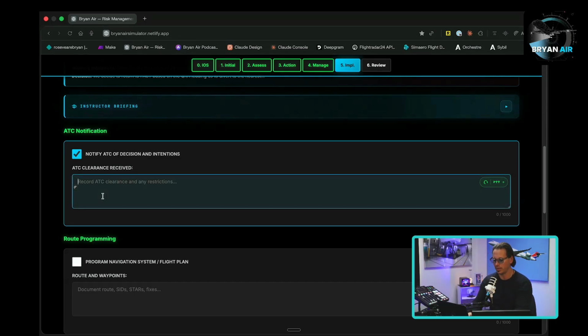So we tell ATC we would like to return to FACT, but they're still pretty close, and this may have taken 20 or so minutes. I don't want to tell ATC we're ready to return yet, because we've still got a little bit to sort out: program the FMS again, speak to our cabin crew and passengers, and let our company know what's happening.